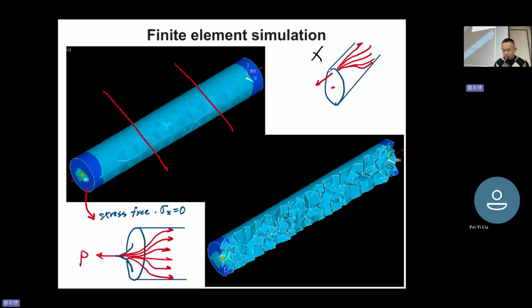But after some distance, you can see that the stress becomes uniform. You can imagine that this is kind of a water source pouring into a tube, and then the tube eventually will have uniform flow in the middle. So that's the reason why we take the definition for the stress using the middle section, okay?